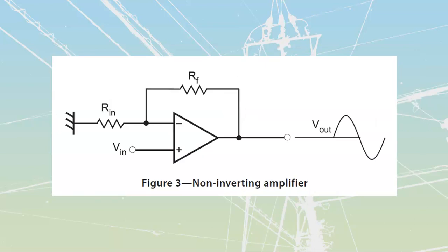Okay, the next one that we're going to talk about is my non-inverting input. My non-inverting input is going to have a similar layout. We're going to have RF over top of Rin, but now we're going to ground that section over here. So we're going to attach this down to a value of 0 volts, and then I'm going to have these two connected in series across to my output over here. This is my input that I'm going to take in values of voltage.